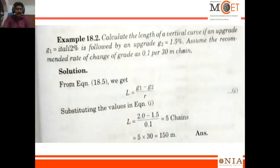Similarly, calculate the length of the vertical curve if an upgrade G1 equal to 2% is followed by another upgrade of 1.5%. Assume the recommended rate of change of grade as 0.1 per 30 meter chain. Same formula. We substitute, both are positive. Here the negative will be retained, which is equal to 5 chains. They have given a 30 meter chain, so 5 into 30 you will get 150 meter, right?